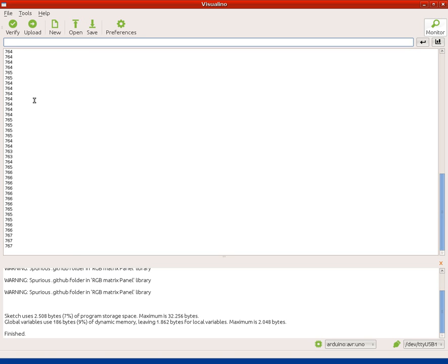So that lets us choose a level or a threshold, so we may have some reaction when there is a change in the light level. So let's say we want to control something by just casting a shadow on the sensor. So I put my hand between the light and the sensor and see the numbers get below 700. So I'm going to use 700 as the threshold for some reaction, and that's going to happen in the next